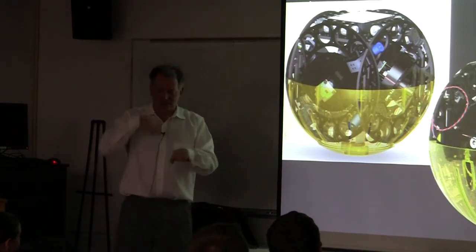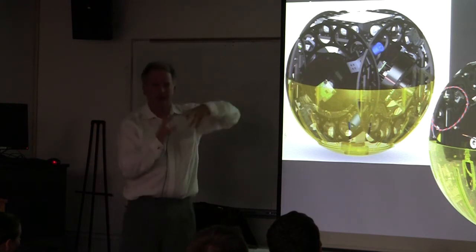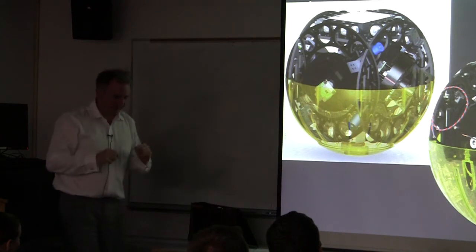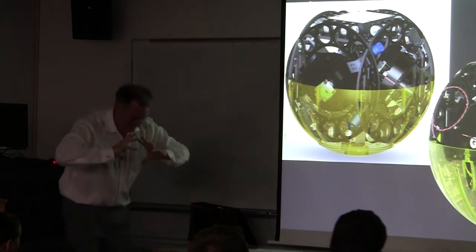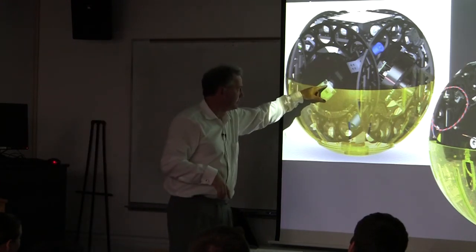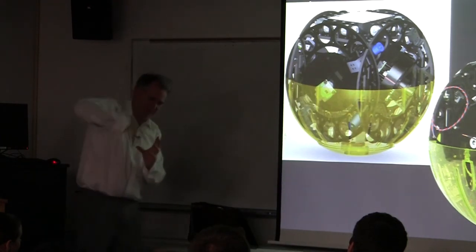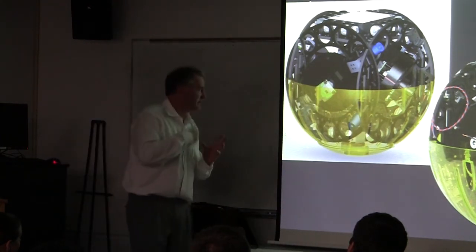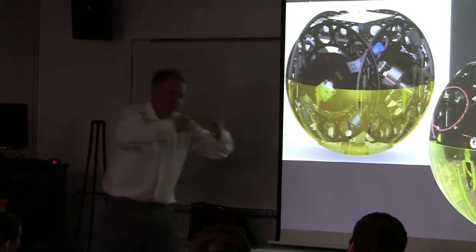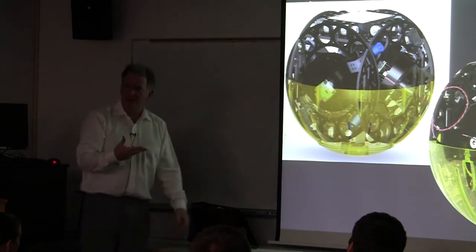And so now imagine, instead of just having one of those heavy spinning wheels, you've got 4 of them, and you can gimbal them in coordination with each other. You get a spherical vehicle, and you can spin up these flywheels slowly with small motors. You can gimbal them with low torque with small motors. But if you spin up the flywheels to 5,000 or 10,000 RPM, then you have very high G onset, and you can get a lot of torque out of this. You can exceed the fundamental performance limitation of the RC car inside the beach ball.